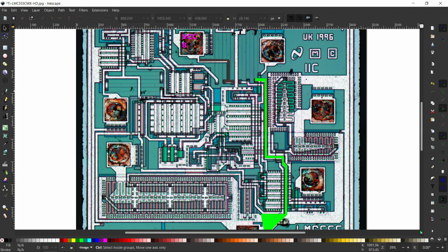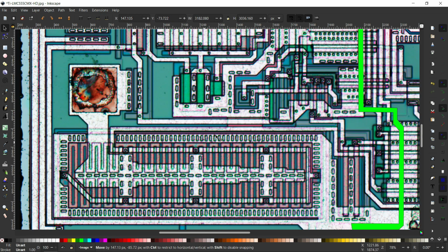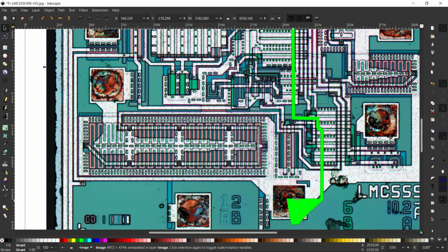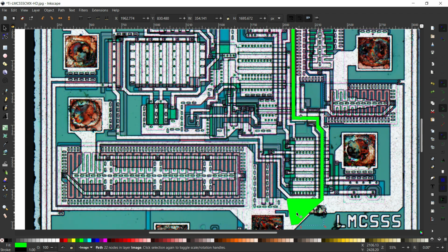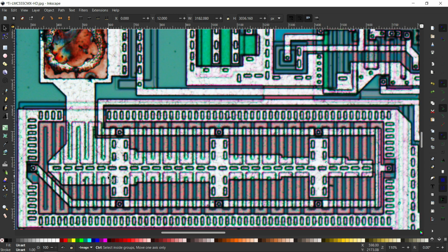We'll come to the bottom side here. See this, you can easily understand which is source, which is drain, and which is the device that is surrounded by the guard ring. Whatever you are seeing surrounding this IC555 is the ground guard ring, because it is connected to the ground pad. We already discussed which is the ground pad. So from the ground pad it is connected around the device, which means it's a ground guard ring. Internally we have source, drain and gate connections.